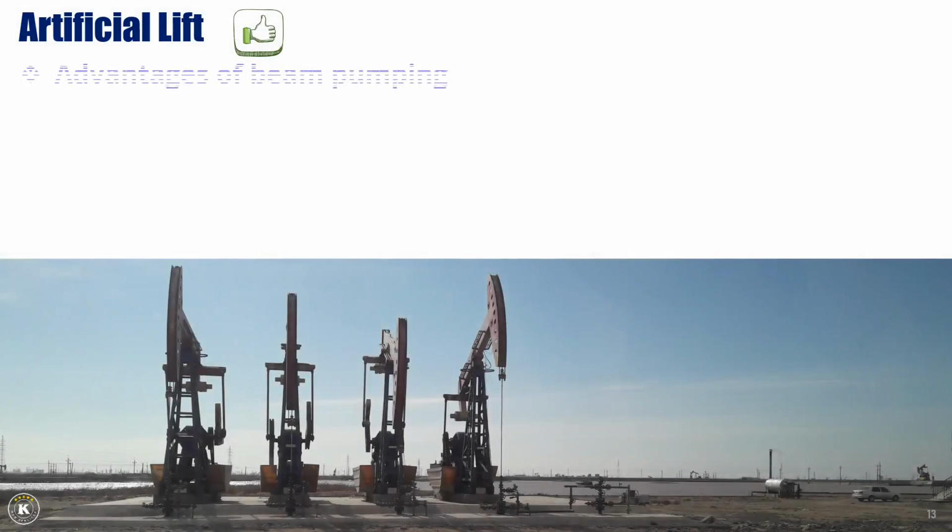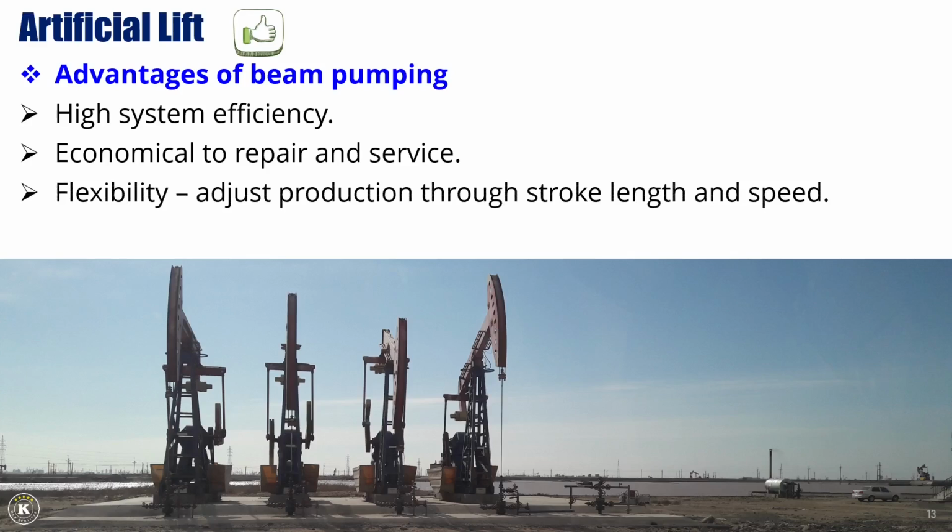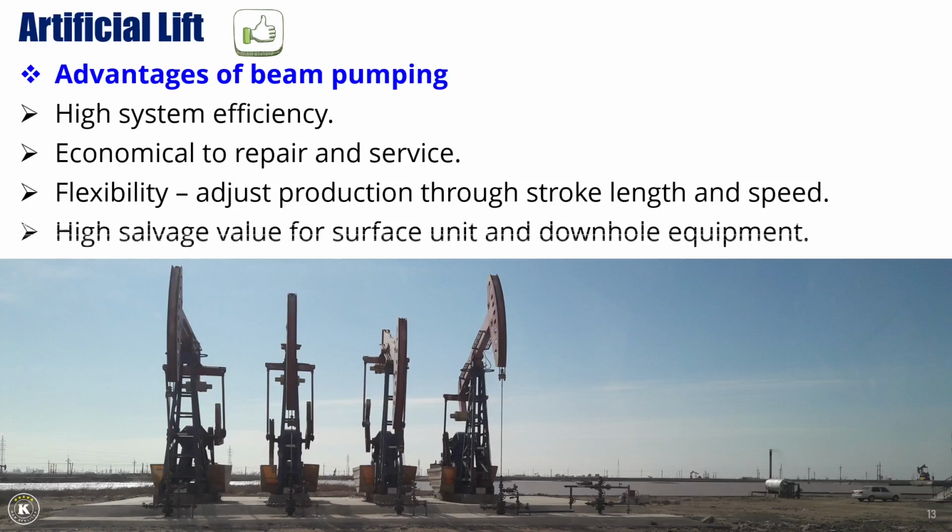Beam pumping offers several key advantages in field operations. First, it provides high system efficiency, making it a reliable and well-proven artificial lift method. It is also economical to repair and service, which helps reduce operating and maintenance costs over time. Another important advantage is its flexibility. Production can be easily adjusted by changing the stroke length or pumping speed. Finally, beam pumping systems have a high salvage value, both for the surface unit and the downhole equipment, which adds to their long-term economic benefit.